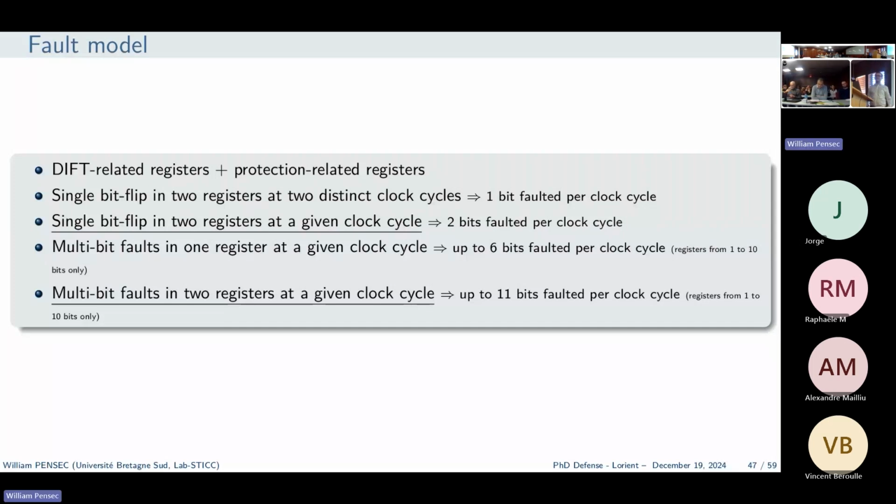Maybe one following Nelly's question about the fact that if we are able to inject faults into circuits, maybe we won't only target the register of the tags, but also the register files themselves. To protect against fault injection, we may also use parity codes, Hamming codes, or SECDED code. And if you do so, I was wondering if you can include in it the register of the tags, and then the overhead will seem to be almost zero.